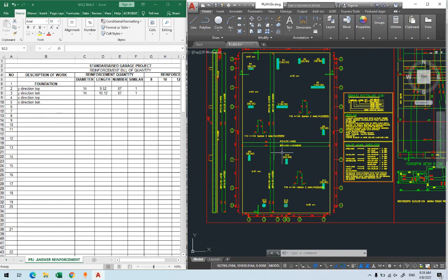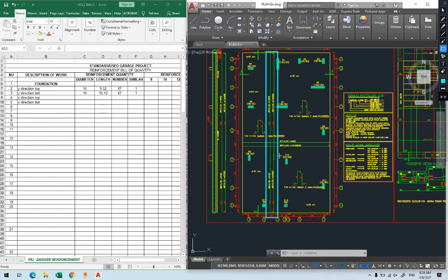So if you realize here, for the side, for this part, you realize there is something twice the information given. One here, one here is given. And you'll see there is a gap here which is not linked. Why? Because when you have a distance more than 12, you have to provide the reinforcement in two steps.